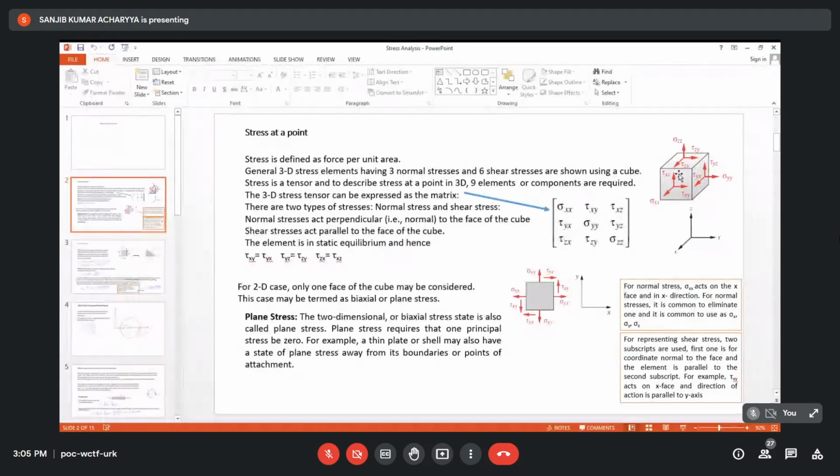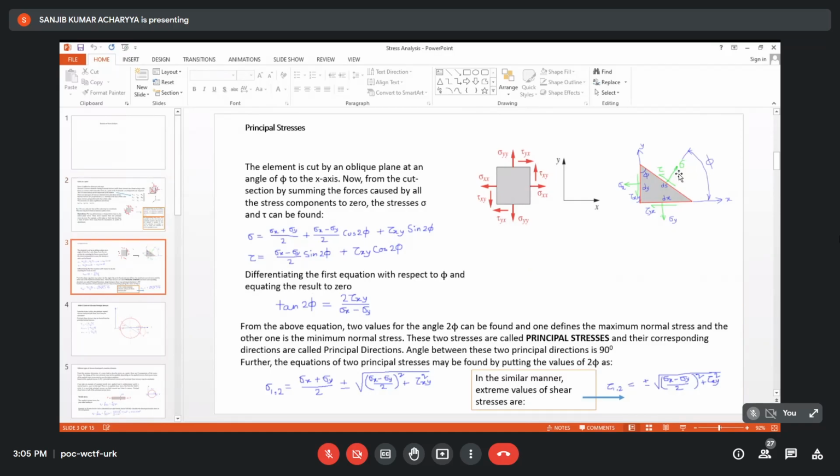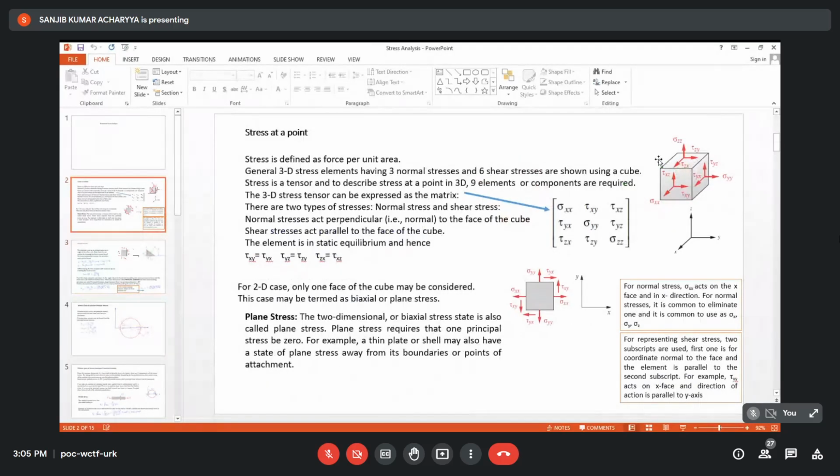Yes sir. Another extreme situation is called the plane strain situation. In this component, stresses will be in all the directions in a particular plane. Stresses will be there in all the directions, but because of the combined strain, force in the y direction will create negative strain in the x direction. If there is also some x direction strain and these two are equal and opposite, then finally the strain in the x direction will be nullified and will be zero. Yes sir. But stresses are present in all the directions.